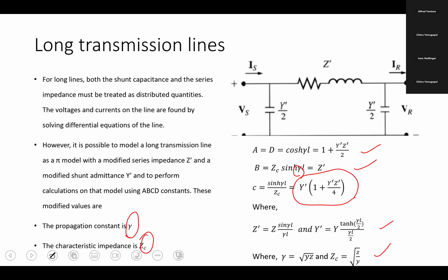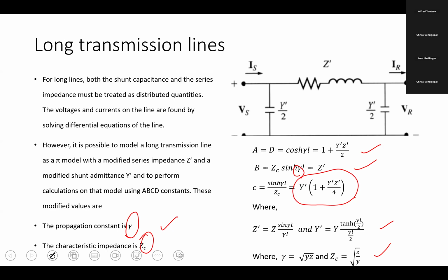So the maximum power transfer theorem is given by this characteristic impedance. So to match the load power with the source power, the impedance of the load must match the source impedance. So match the impedances at both sides, then you can get the power transferred through the lines maximum. Okay. Right.